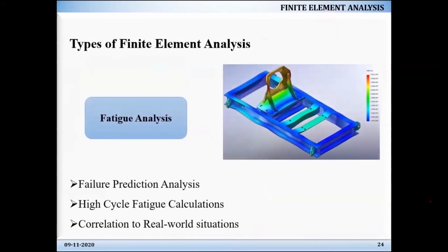Next, you have something called fatigue, one of the areas which is predominant nowadays, high cycle fatigue. Fatigue is mainly responsible for sudden failure. If you recall your basics of engineering, fatigue is very dangerous, because by the time you see the crack, it would have failed. It never gives you a chance. There is no deformation in the case of fatigue, whereas most components give a visible indication that they are going to break. But if it is going to fail by fatigue, there is no visible indication at all.